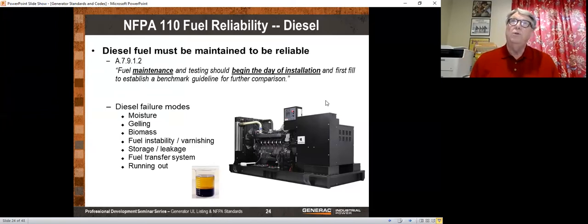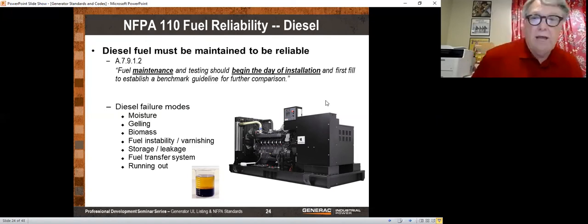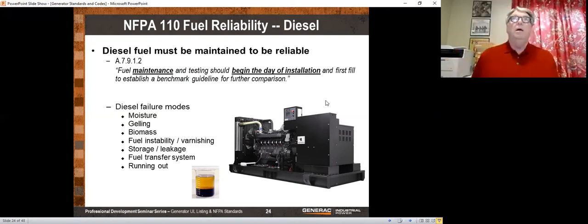I have told this story, I think, before. It's like people with only a hammer think everything's a nail. And I'm kind of like that because I'm an electrical guy. And I remember being up there testing a generator that was having some instability problems, and we thought it was due to electrical harmonics because there were drives on there. And we spent like a whole day trying to figure this out and trying to reduce the level of harmonics and so on and so forth. But Generac, at least with their three-phase RMS voltage sensing, have been very, very reliable in terms of harmonics.